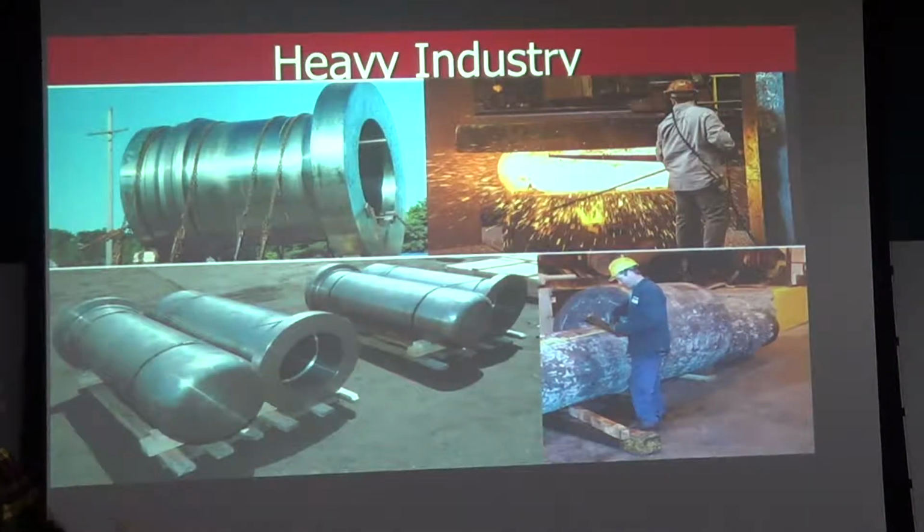In the case of that particular forging, it's for a large press, where you just have a single item to be actuated. You could make something like that with multiple throws on it, and then it would become a camshaft or a crankshaft for an engine. That was not for that application, but they do make large engine cranks, say for locomotives, out of forgings in a similar way.